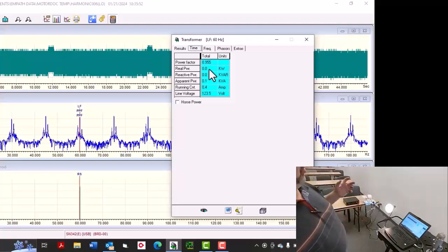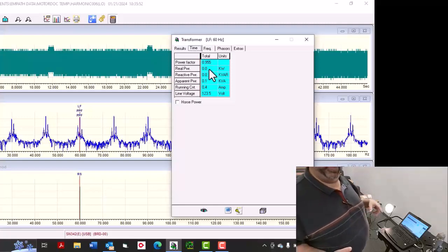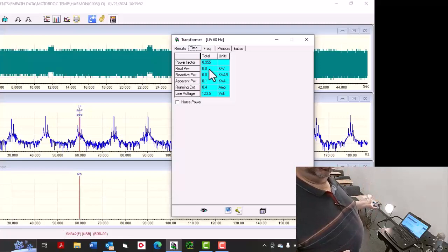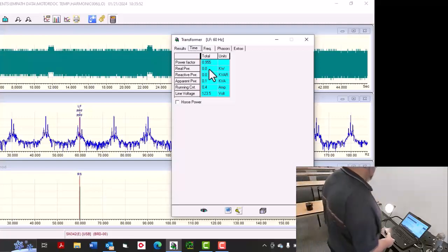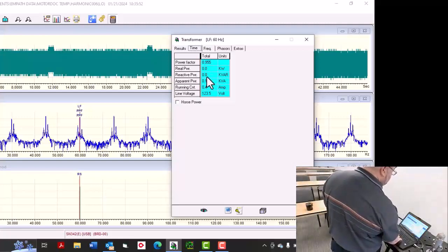Okay? So what is the impact of the overall harmonics? And what we found in the field is the harmonics that we're seeing as a direct result of that notching, when it feeds into neutral, will generally eat up a huge chunk of the savings you see in an LED system. So we need to consider that as we go forward.